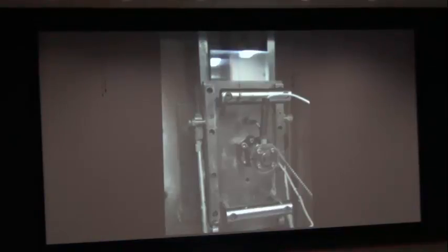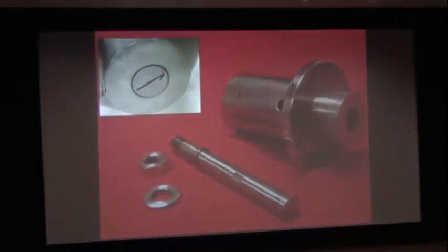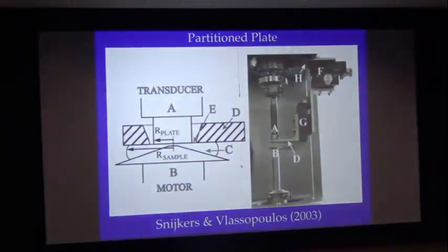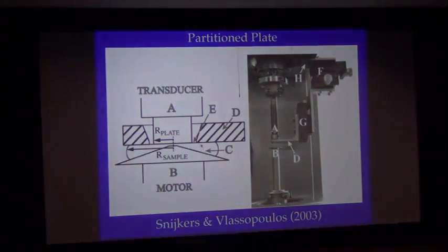Okay, that shear fixture is about 75 pounds, takes about 3 or 4 hours to heat up before you can start doing experiments. This is the way we used to do them, but nowadays there's a series of commercial rheometers available that use sort of the same idea. Instead of measuring the total torque, they put a partition here. See a little gap here. So they just measure the torque in the middle of the sample away from the offending free boundary flows in a rotational geometry.